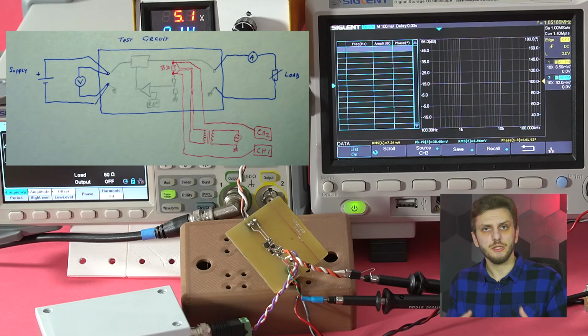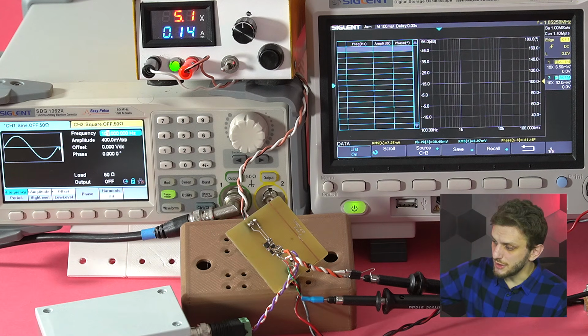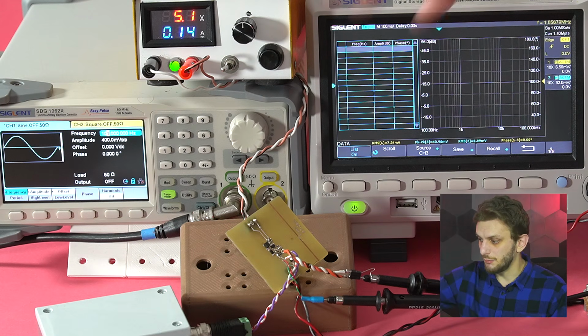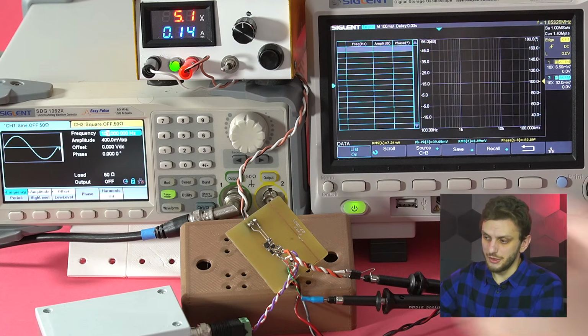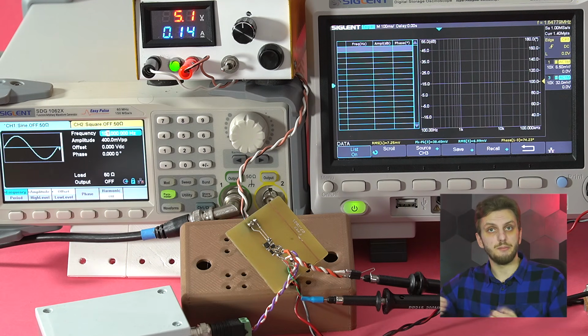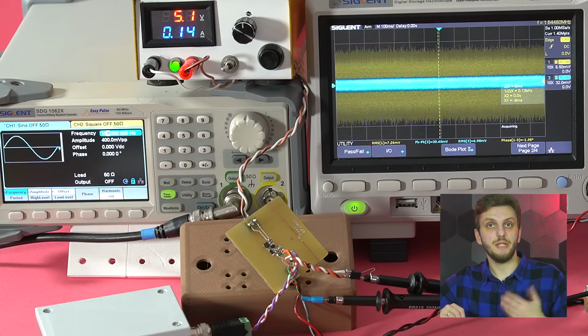So both of these need to be monitored, and it's important to take into consideration that the power supply loop will have different behaviors under different conditions. So it's important to perform this test under multiple load values and input supply voltage values. Now, specifically for the loop measurement, I'm using an oscilloscope with signal generator coupled together in Bode plot mode. So you could of course do the measurement manually by injecting signals step by step and then measuring the amplitude and phase ratio. But if you have a piece of equipment that can do this automatically, it just saves a lot of headaches.